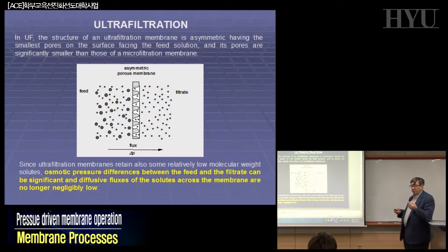The asymmetric membrane was the origin of a system that was becoming of practical interest, because before, the same materials were giving transmembrane flux very, very low. They invented these membranes. Suddenly the flux was 100 times bigger, of industrial interest. From this moment, everything started, already in the 70s. But just to realize this asymmetric system.